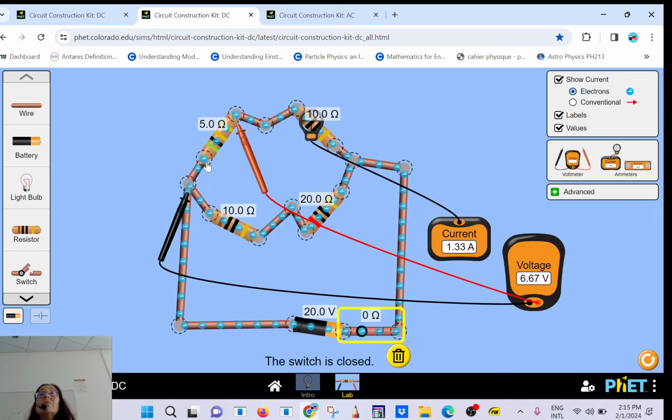Which means that the hot connection will be plus, minus, plus, minus, plus, minus. But the peak value is not going to be 120, it's going to be more, right? I will show you how to do the computation. It's going to be 170 volt.